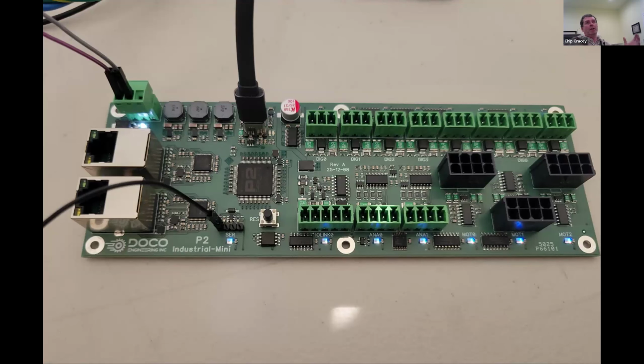And then in the bigger picture, you're shifting out 24 bits of first red, then green, then blue data. At the end of that 24 bits, which is one LED's worth, you pause, you hold low for, I think it's 1.2 to 3.6 microseconds, basically 1 to 3 normal bit periods. You just hold it low. And then you give it the next 24 bits and do a little short pause like that. And then when you're all done, you hold that line low for 50 microseconds plus, and the LEDs recognize, oh, that's the whole frame, we're done.